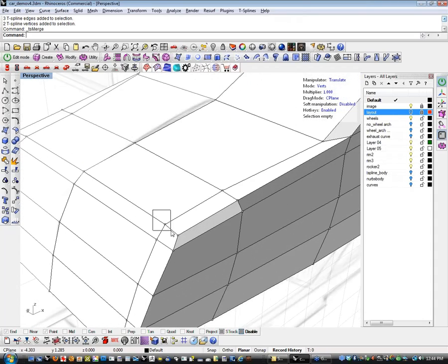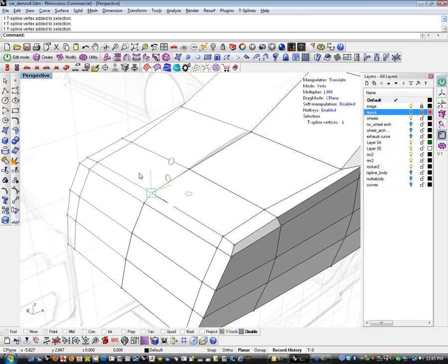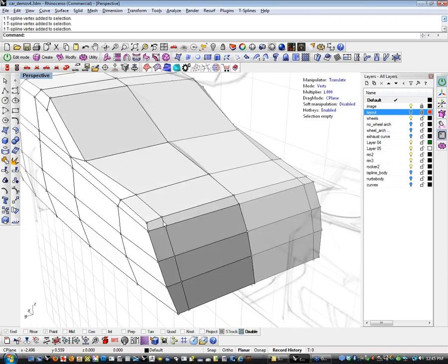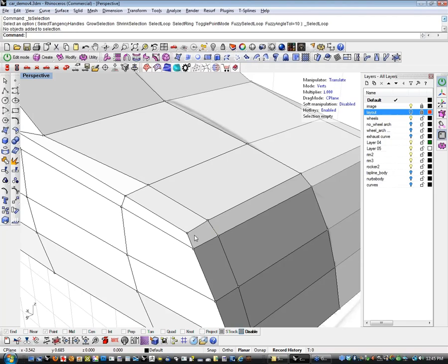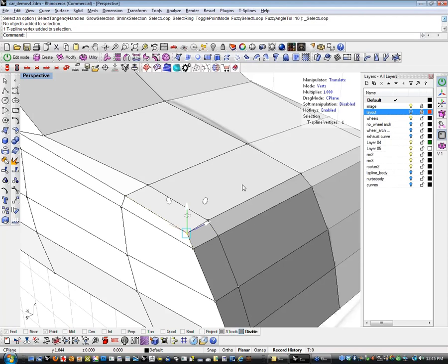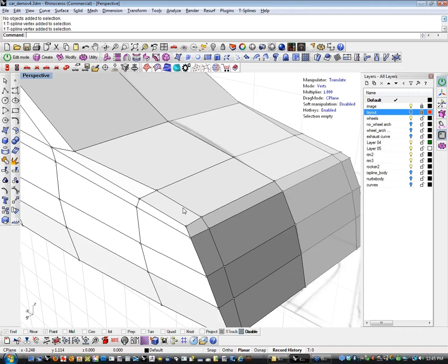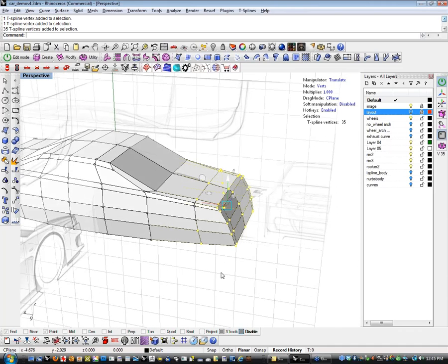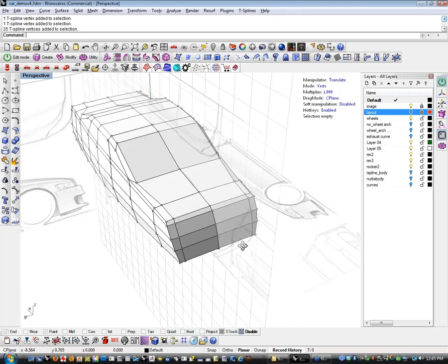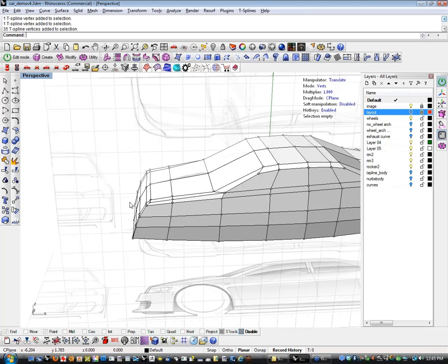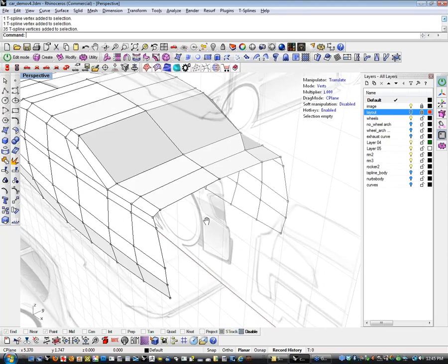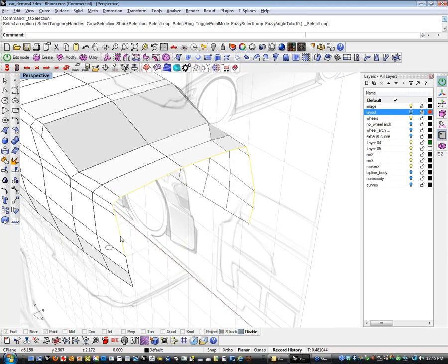Now, one thing we want to check, make sure that anytime you do an operation like that, especially when you're getting started and it's really easy to make duplicate faces and all sorts of screwy stuff, that when you join 2 surfaces up like that, or two sets of patches up, select your verts and make sure that you've only got 1 vert there. If you had 2 verts here, then something joined but something didn't join, and the way to fix that is just to select it and hit the Z key or the weld verts button, and anything that's coincident on top of each other within file tolerance is going to stick together at that point, and you'll clear that up. So we'll weld the back so that you can see the 2 different ways of doing this.